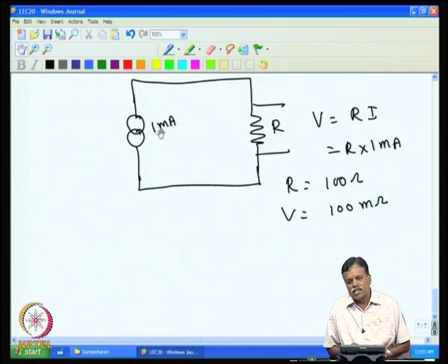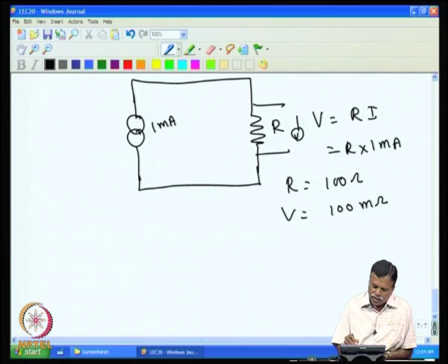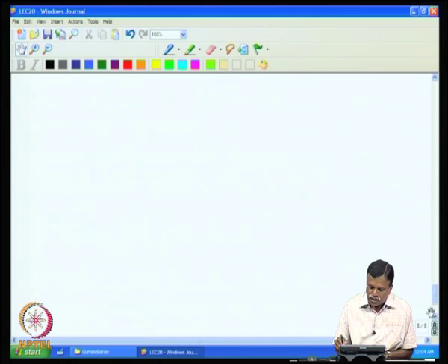because the resistors and the capacitors, the operational amplifiers, all of whatever I am using, or the reference voltage that I am using, all of them will change with temperature, and the net result would be this current changing with temperature, and then whatever measurement we make may not be accurate. And also we will have to put some voltmeter or some measuring circuit here to measure the voltage. This also will drift with temperature. So, the net result is you will have error due to this current change, and error in the voltage measurement. This will make the measurement not very accurate.